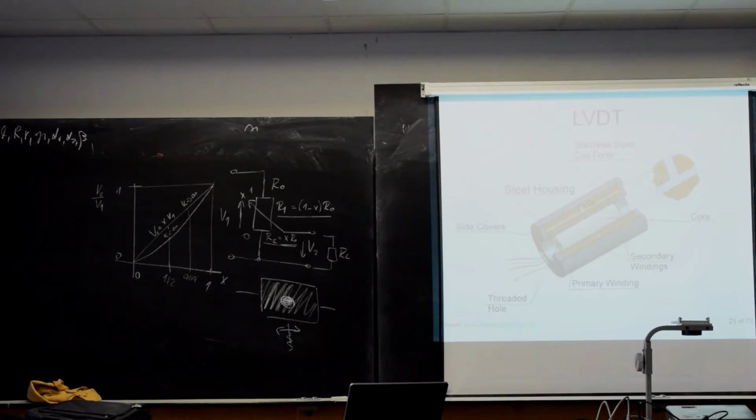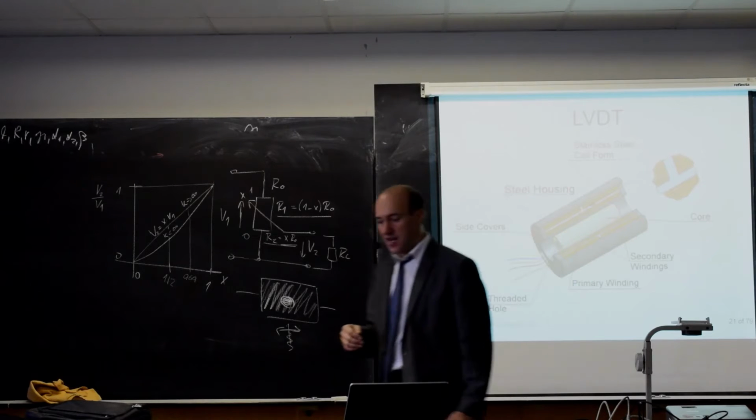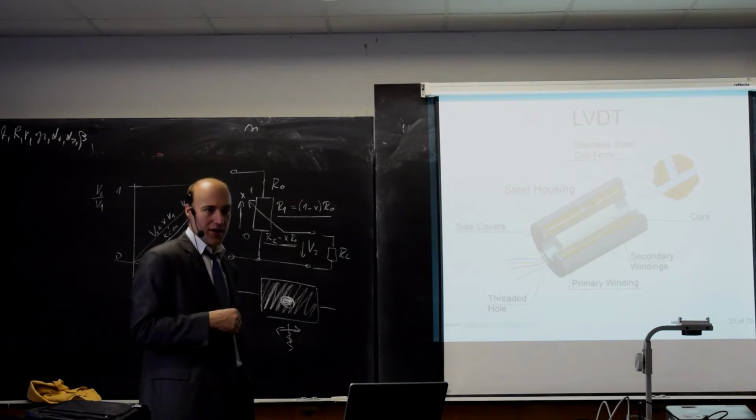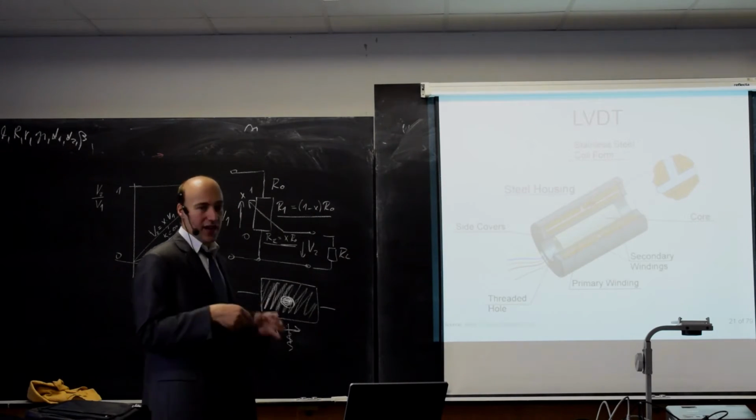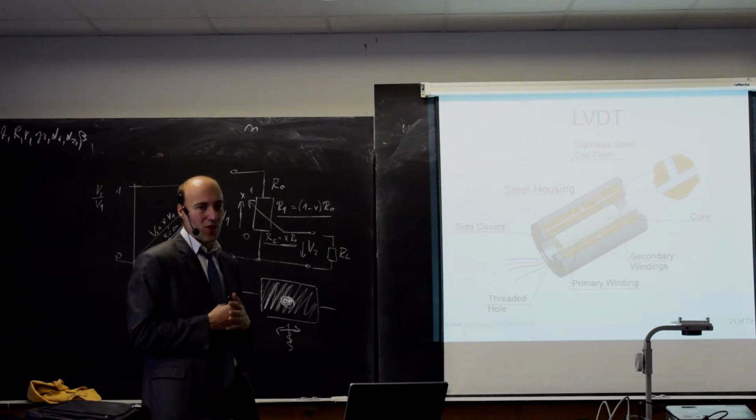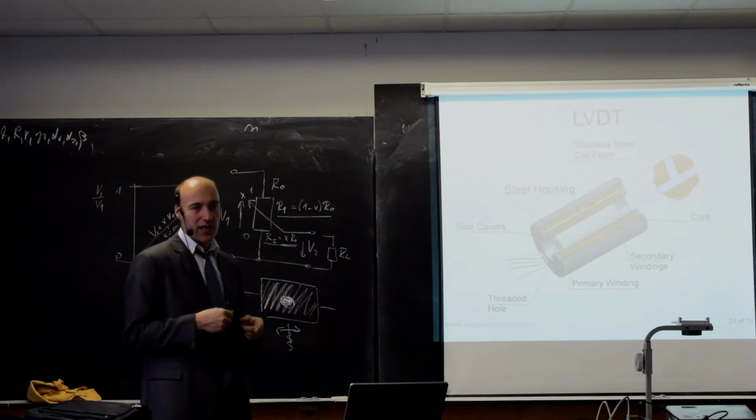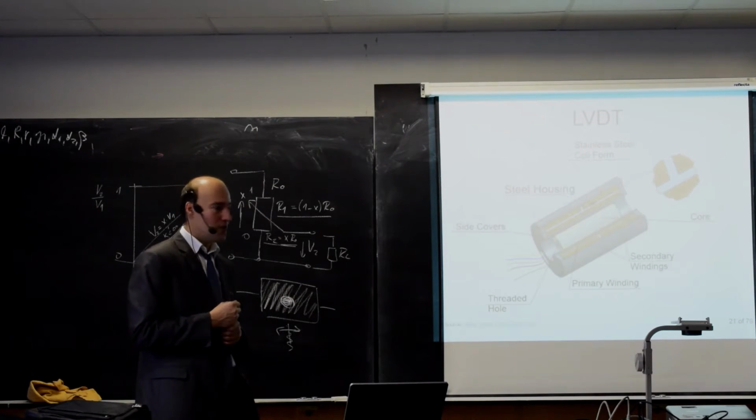Here is the movable part. So you connect this to a frame, and you connect this to an object, and then this gives you the position. This sensor has current output from 4 to 20 milliamperes. So although internally the signal is voltage, it is converted to current. So there is an additional electronic circuit and operational amplifier that creates current from voltage.